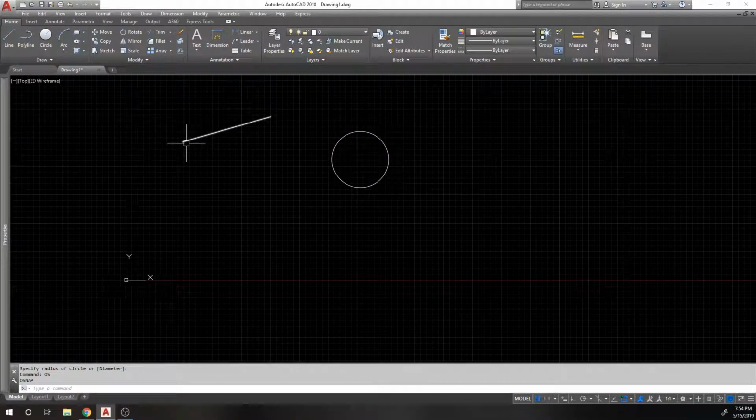But let's say I want to snap to the end of this line. I invoke the line command and type in end. I'm in the middle of a command, and this only works within a command. Outside of a command it won't really make sense. AutoCAD will tell you it's not a command. Watch this, I'll type in end outside of the command, and there's nothing there. We'll just discontinue that command. If I typed something else, like quadrant, it does something completely different from what I want.